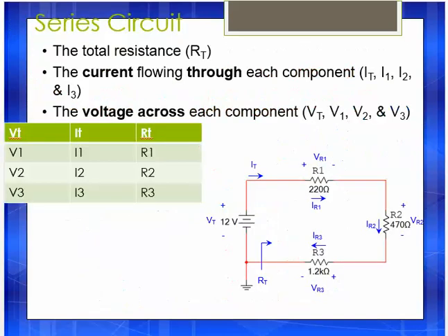Okay, one of the things that I'm going to ask you to do quite often is fill in the box or fill in the chart. The way we go about doing that is we're given a schematic here, and this is a series circuit because as we look at it, as the electricity flows, there are no multiple paths. Up here they talk about IT going this way, and that's because they're talking about the conventional current, not the actual current.